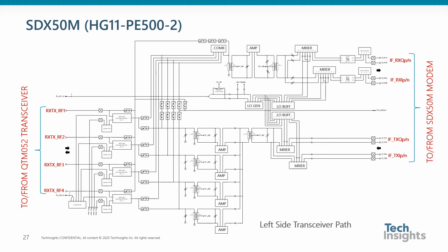The differential signal goes through an amplifier stage and another transformer. It is then split into 2 paths, each path passing first through a capacitor before going to a pair of mixers. Each mixer receives a different pair of LO signals from an LO buffer in order to generate quadrature IF signals. The in-phase and quadrature paths each pass through a respective passive filter. The filter signals then pass through an output driver to drive the external output pads, which are then routed to the modem.